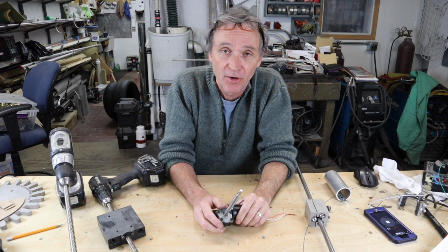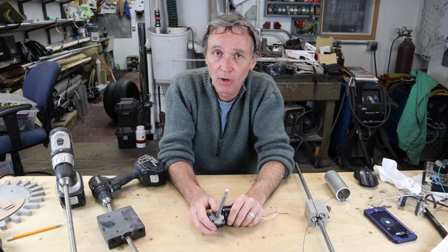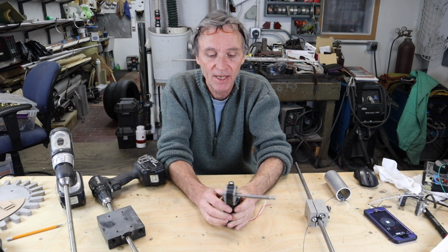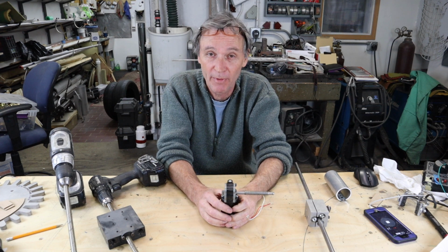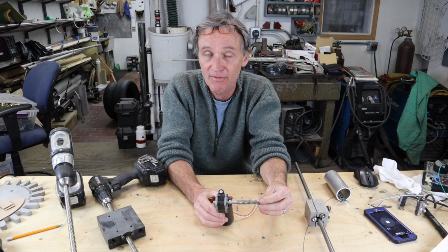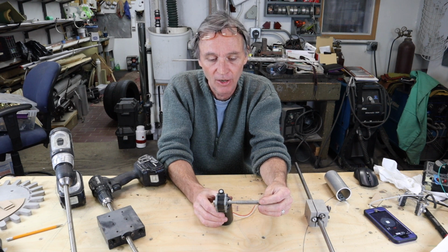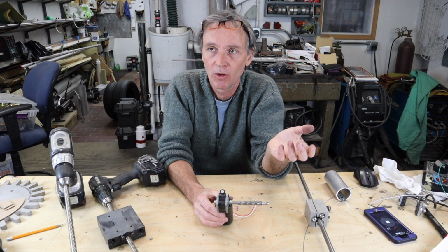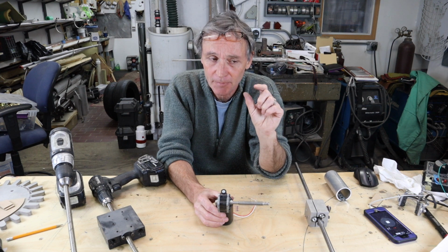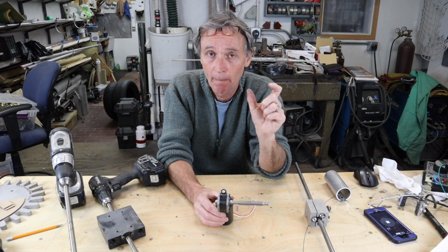So another way to turn rotary motion into linear motion, i.e. this from this, is to use what's called a lead screw. A brand name you may be familiar with or not is the Acme thread. Basically what it means is it's a very coarse thread. So normally a 1/4 bolt means that it's a 1/4 of an inch thick and it has 20 threads per inch.